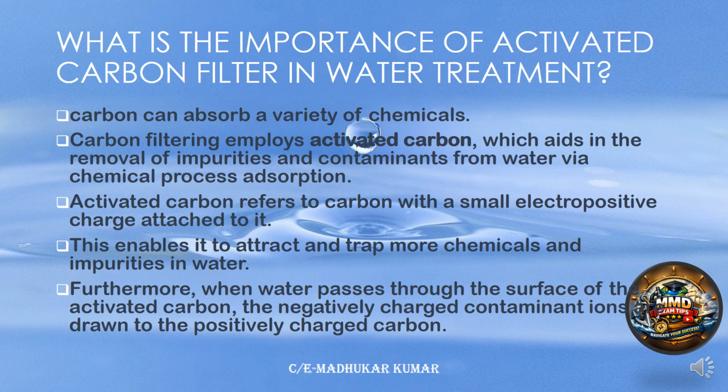It has absorption and adsorption both. It is slightly electropositive, so whatever electronegative, negatively charged contaminants are in the water are attracted towards this and attached to the positively charged carbon atoms, and they are going to clean the water.